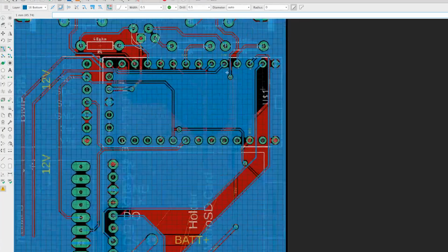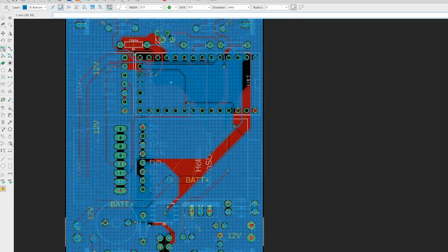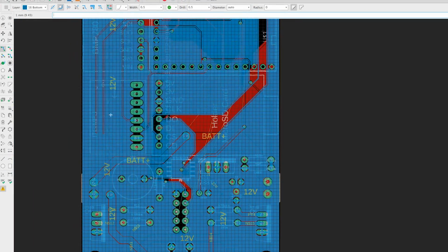So if I can't fully connect the air wires, or if I'm not feeling confident enough in my design yet, or if the air wire is really long or something like that, I can just bring all of the signals closer to their targets. So these thrust vector control servos were originating from these far away pins, and they have to go all the way down here. So what I'm doing is I'm starting to draw the route as it goes down.